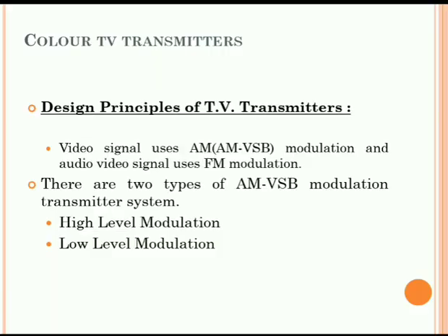Synchronization happens between the transmitter and receiver by adding synchronization pulses in the video signals. Then audio information is converted into the electrical signal by a suitable microphone. We know the microphone, as you might have seen in the mobile phone: whatever the video signal is stored by using the video camera, and whatever the voice in that particular video signal, that is stored by using the microphone. Video signal and audio signal are modulated, and both the signals are then combined and fed at the transmitter antenna. This is what happens in any television transmission system.